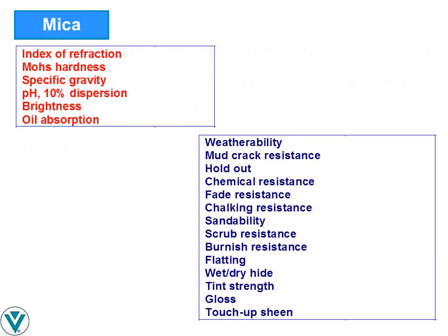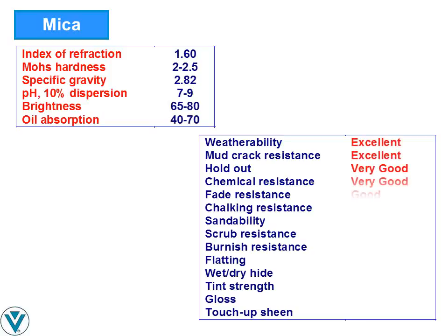Mica does not delaminate quite as readily as talc, so it is somewhat harder, although still softer and less abrasive than most other fillers, minimizing its contribution to abrasion resistance. Its high aspect ratio and platy shape provide excellent film reinforcement, but at the expense of optical properties. The relative performance of mica as a coating filler is seen here.